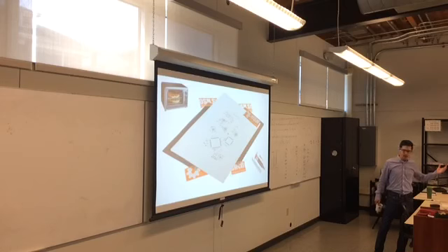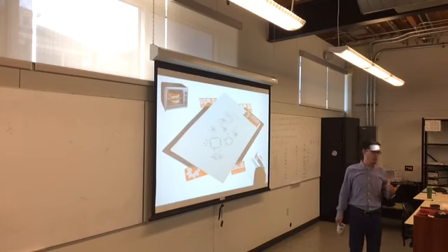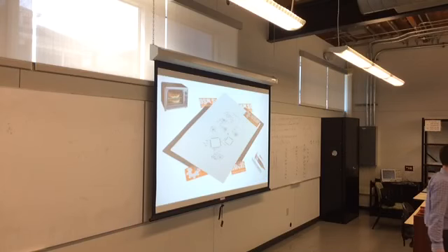Karen, Ben? All right. A couple things you can do for your first run: if you've got discrete through-hole components, you can just drop them into the board. A very cheap, easy way to do this is, if you're working with this chip and you want to make a PCB just so it's all physically laid out the same, just make two rows of DIP through holes and just stick this in and solder it.